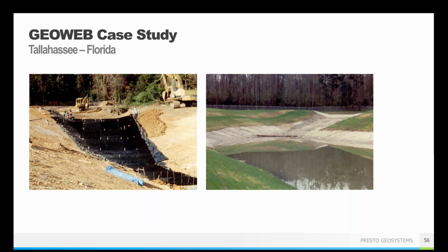So they wanted to collect the water and send it down this flume and down a spillway apron into a holding pond that was designed to capture that runoff from this whole big medical facility. So they knew that they were going to have very intermittent, but potentially very high flows during those storm events where they were collecting water from this large site and directing it into this holding pond.